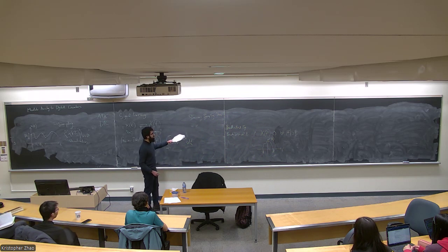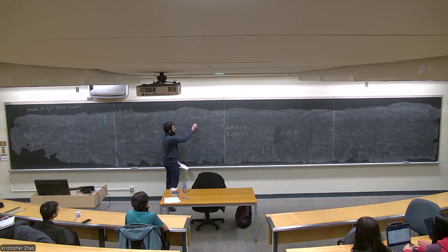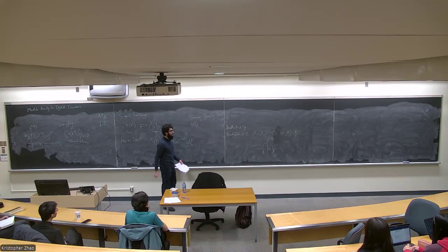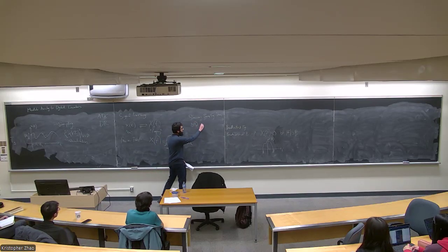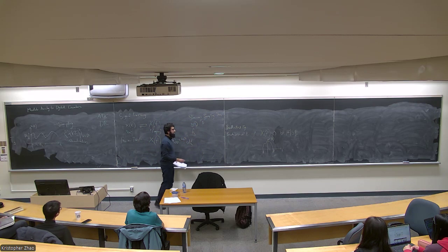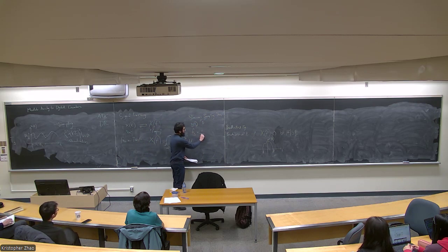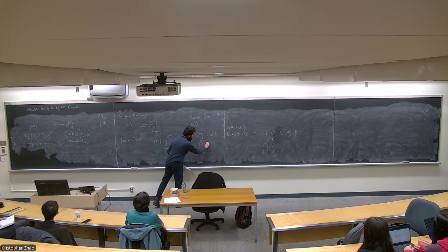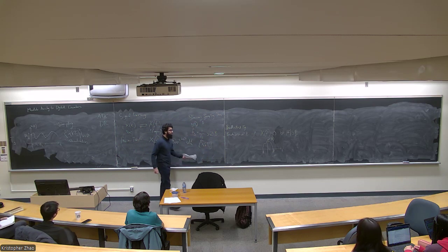So what the theorem says is, if you're given some continuous or analog signal x of t that has a bandwidth of B, then the only requirement is that your sampling rate, denoted by fs, which is just the inverse of the sampling period, is greater than 2 times your bandwidth. Then all those samples x of kTs fully represent the information that was in the continuous signal x of t.